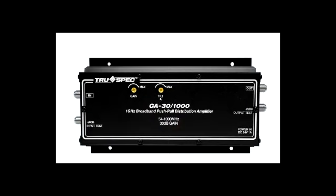It's the same thing, right? So then you're going to amplify the higher frequencies way more than the lower frequencies. So by the time you get to the end of the channel, the end of the run, the frequencies are going to be sort of like equally strong. So the lower channel frequencies are going to be nice and clean on the television set, and the higher frequencies are going to be nice and clean also on the television set. Right? So there's a balance between how strong you want to push that signal, and depending on that, how you want to adjust the slope or the tilt of that.